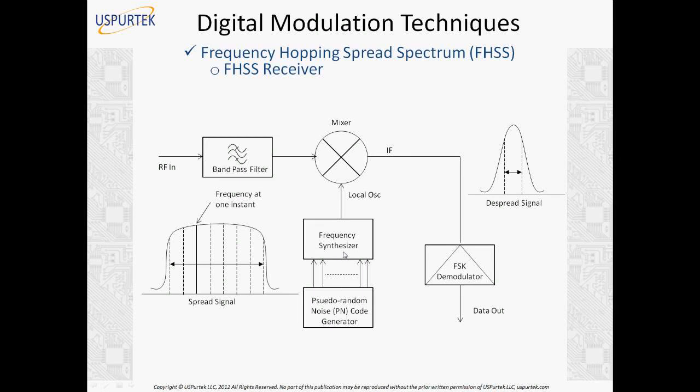But despite that, it still finds use. So the FHSS technique finds use in some machine-to-machine communications, which is an intensive area of research these days. It's intended to connect devices together. Now there, the requirements are different. We don't have the same requirements as in cellular communications. So there, FHSS finds use because the reliability of the signal or information that is sent is more important than the bandwidth or the data rate and other things.